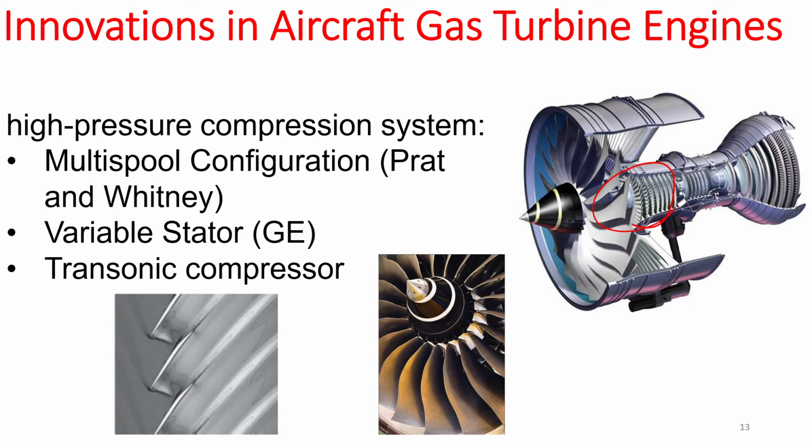And we can also have the transonic compressors, because this transonic compressor is actually a very important part of these innovations, because compression at supersonic and transonic speed is always a huge problem. In the supersonic speed, you usually use ramjets and scramjets, so we don't really do the classic compression, if you will, gas turbine compression.